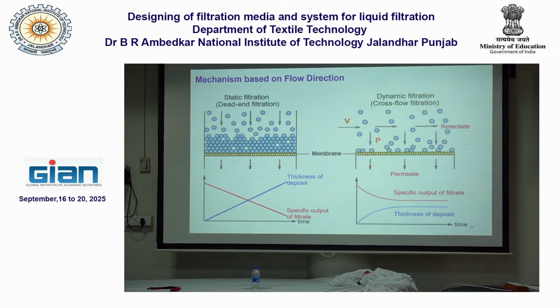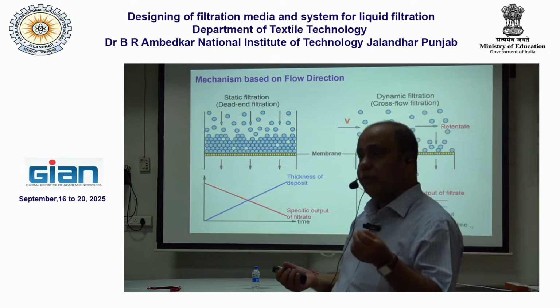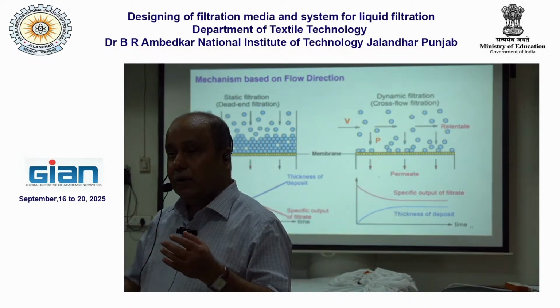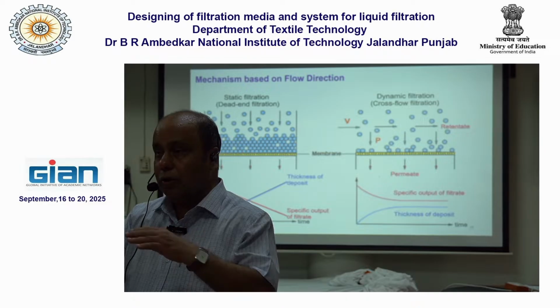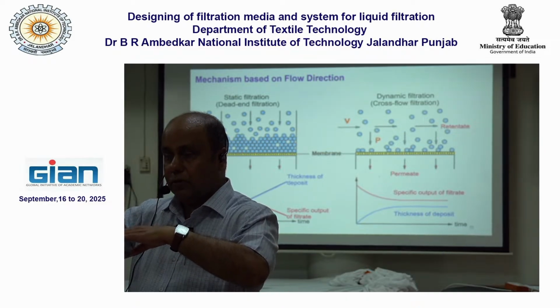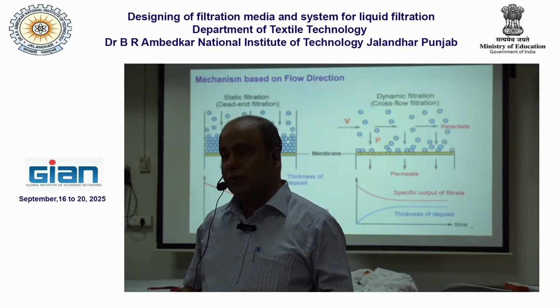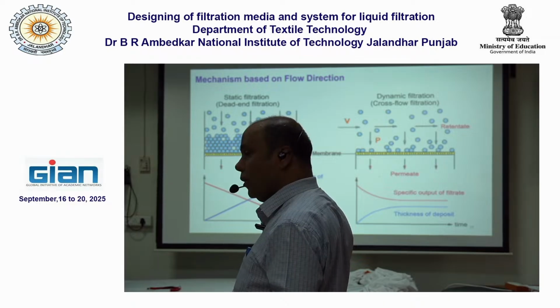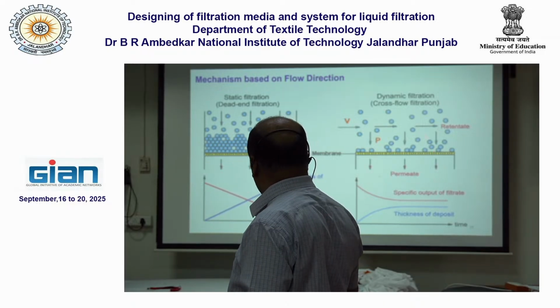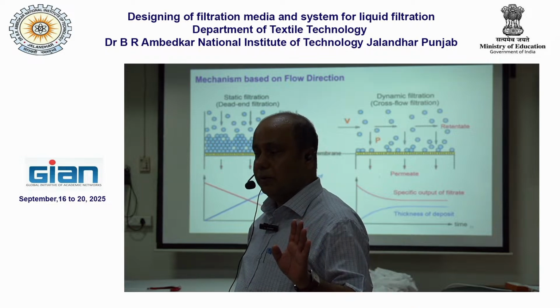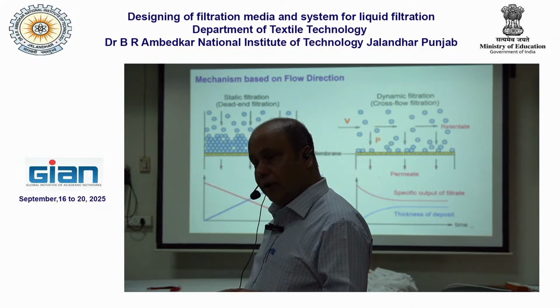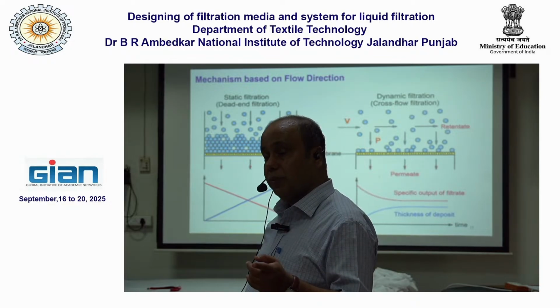Cross flow filtration may have blocking filtration without cake formation also, because if the contaminants are very less, for example, if you want to remove virus or bacteria, which are very less in number, you may not have cake formation. So it is not always that you have cake formation. It all depends on the situation. But in this case there is a possibility of cake formation also, but in this case there is no cake formation. So you can have cake formation and no cake formation. Both are possible. Both pictures I have shown you.